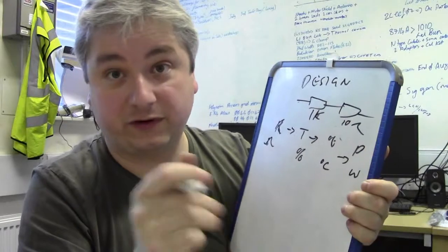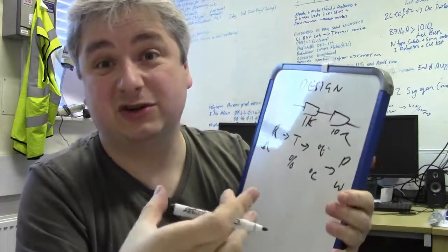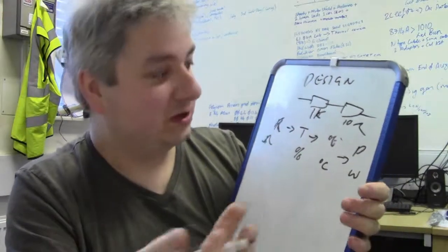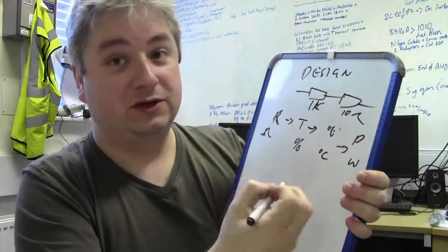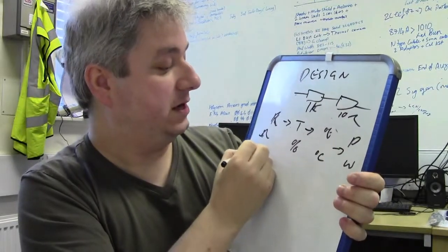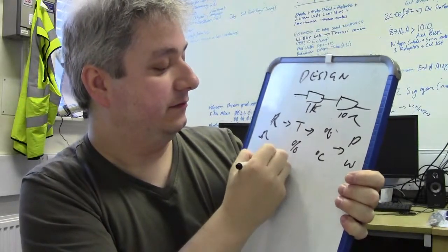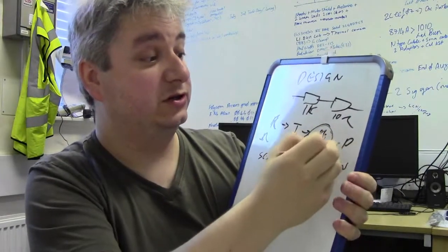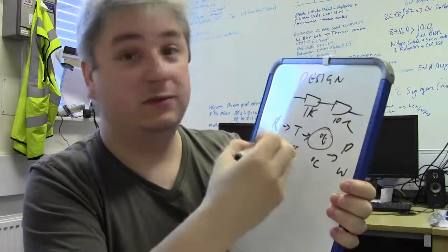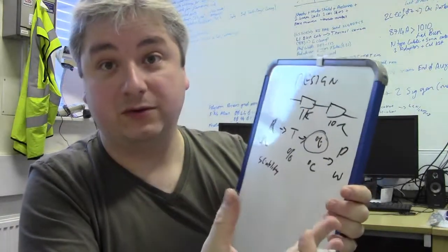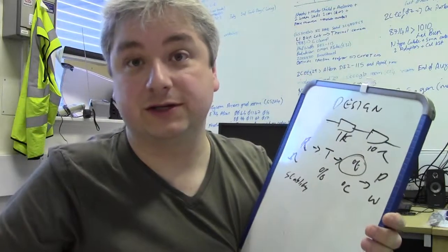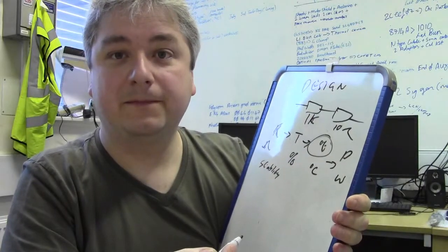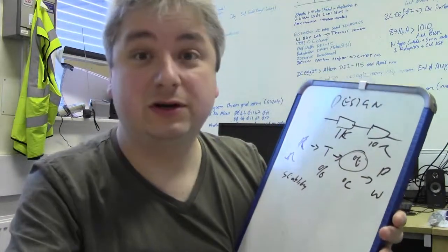Okay, you've got current flowing through it, you develop a voltage across it, it's going to start dropping power. It's going to start heating up. Yeah, power. You've also got stability, which you're never told. You're not really told about temperature coefficients. You might touch on power, you may do Ohm's law, you start working out what's the power across this resistor. It's all very well and good, but they don't actually tell you that a resistor can only take so much power. That's why you've got so many different types.